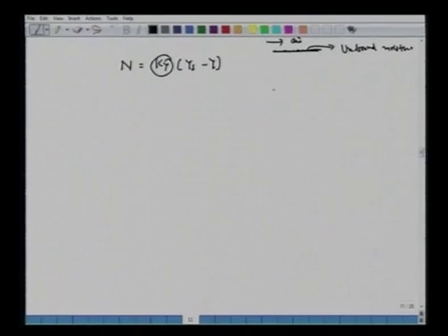So water evaporates, we have done this earlier. The moisture on the solid surface evaporates. There is airflow, so there will be some concentration gradient. This Ky is a function of Reynolds number, Schmidt number, and depends on what velocity we have, etc. What is Ys? It's the moisture content in air at the solid surface.